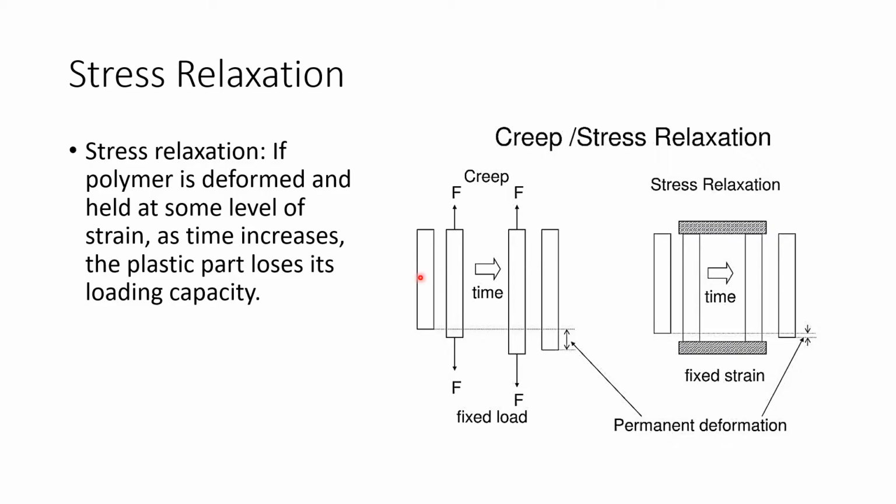Stress relaxation, another application problem. If a polymer or your plastic is deformed and held at some level of strain, and then time continues, the plastic part is going to lose its loading capacity, okay? Because it has to be holding something, and you have a deformation in it, so it can't give full loading capacity. So stress relaxation means that because of the stress, the plastic is losing loading capacity, yeah?